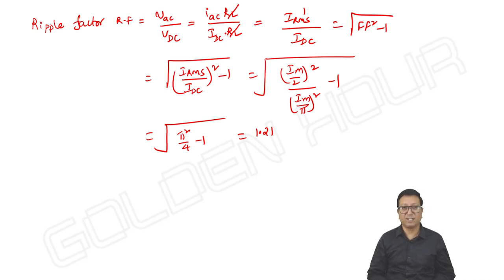Okay, so this is the first parameter and its significance. Why we are calculating? Earlier in my previous class, I just gave mathematical explanations, derivations, etc. Now you can understand. In the rectifier, our concern is to convert AC into DC, but secondary voltage is a pure AC signal, but output is not pure AC. Output is a combination of DC and AC. And so in the output, what is the amount of AC present, and what about the DC component? Amount of AC by DC, that is defined as the ripple factor. Ideally, its value should be 0, but practically it should be as small as possible.